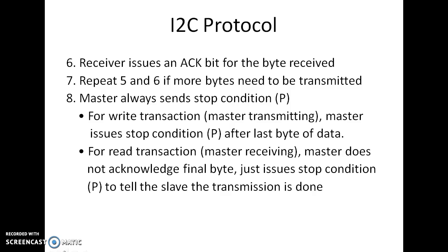The master always sends the stop condition P. For a write transaction, where the master is transmitting, the master issues the stop condition P after the last byte of data. As well, for a read transaction, where the master is in receiving mode, the master does not acknowledge the final byte. It will just issue the stop condition P to tell the slave the transmission is done.